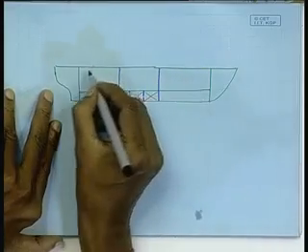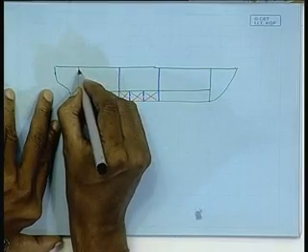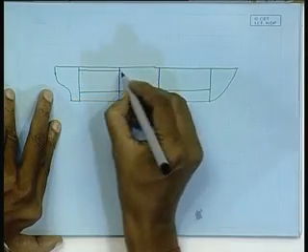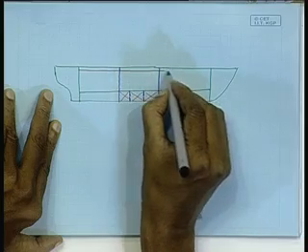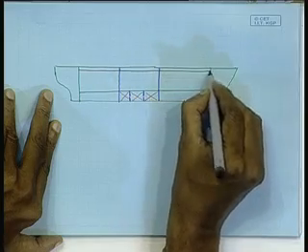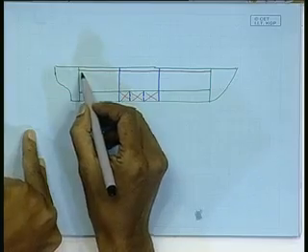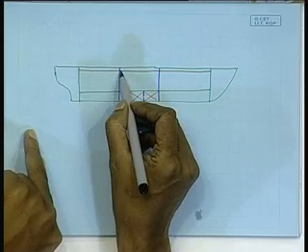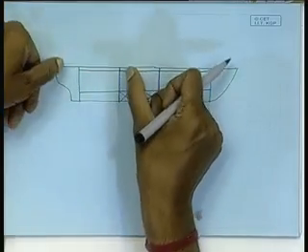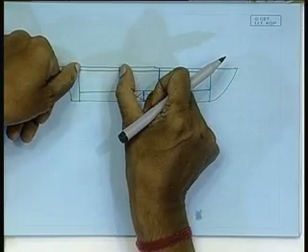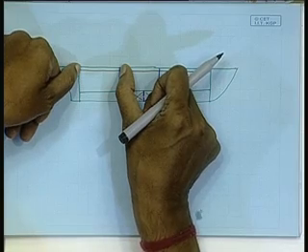Say the deck is longitudinally stiffened, what does that mean? A longitudinal stiffener is running like this, right. It is piercing through the bulkhead, and then the transverse bulkhead will be sealed off by those plates, as we have shown, right. So now in such a case, what appears? It appears as if the longitudinal is supported between these two points, because they will be welded at the bulkheads.